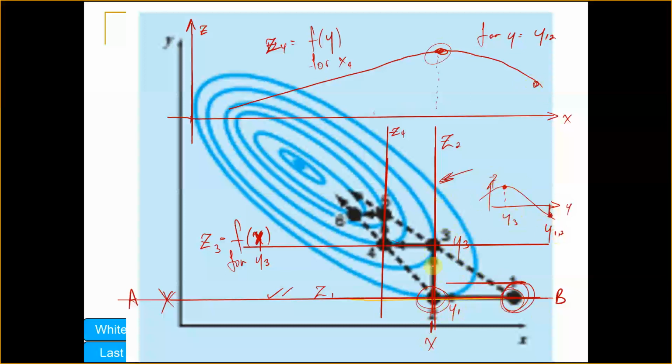The peak, if you are on this line, it's hard for you. Map reading would help. But it's a rule of thumb. You understand what a contour is, right? A contour is a line of constant height, or in this case, a line of constant z. So the rule is, whenever a line becomes tangential to a contour, you're at the peak or the minimum of the line.